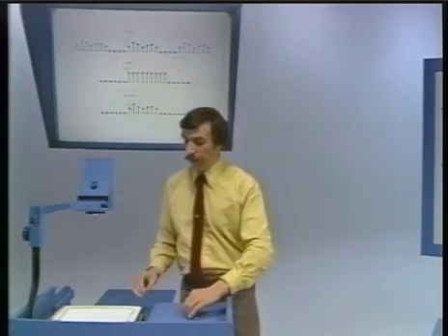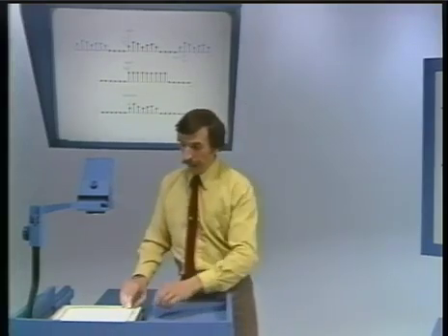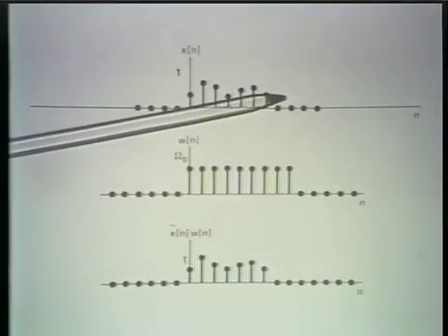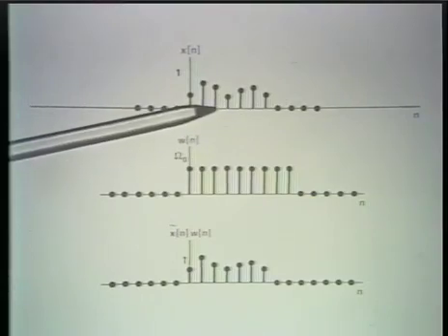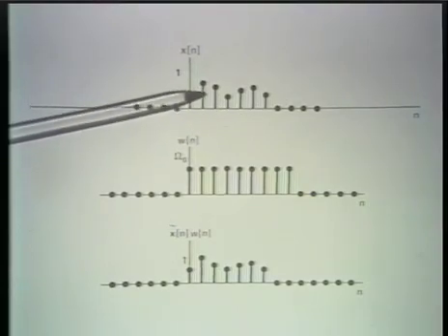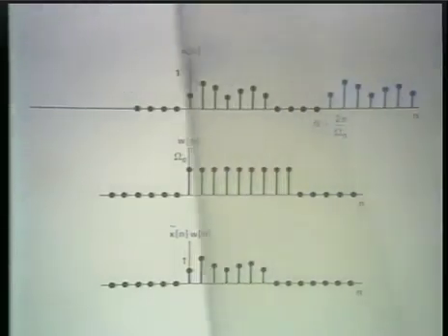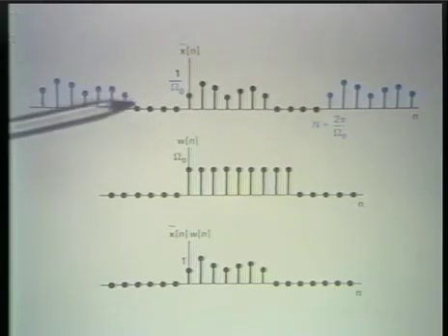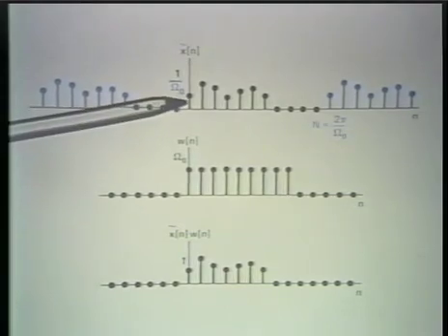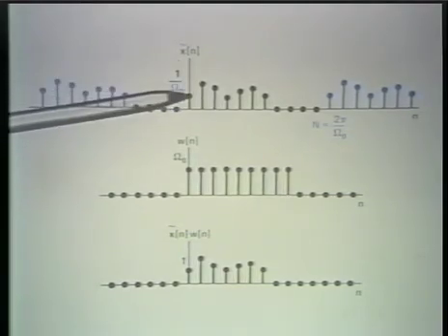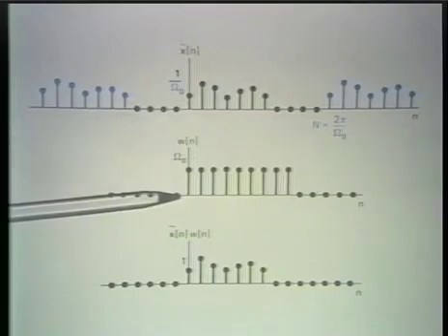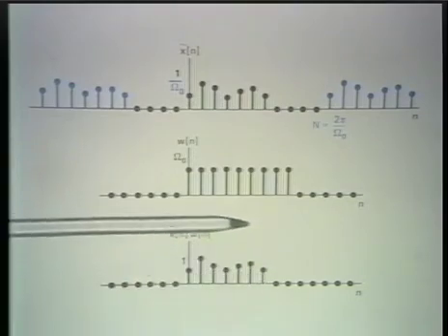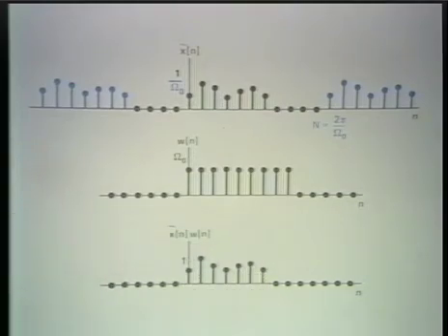Namely, if we have a discrete time signal of finite length, and we sample its Fourier transform, the time function associated with those samples is a periodic replication, and we can extract the original signal from this periodic signal by multiplying by an appropriate time window, the product of that giving us the reconstructed time function as I indicate below.